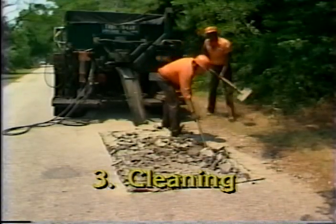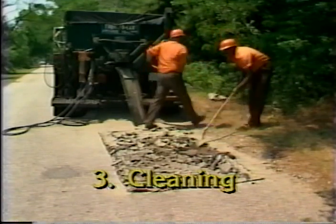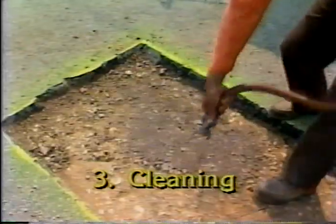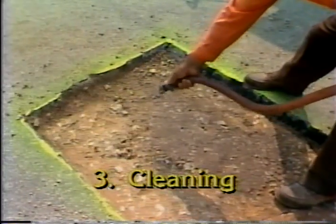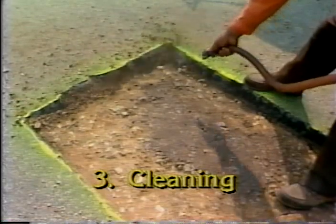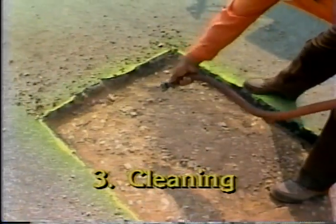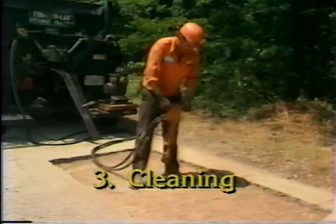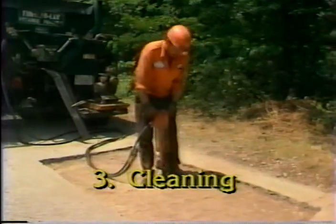3. Clean out all loose materials. Remove the large materials with a shovel and the small materials with a broom and compressed air if available. Remove any water and dry the patch area completely if it's wet. Tamp the bottom of the hole to compact the disturbed base or subgrade.